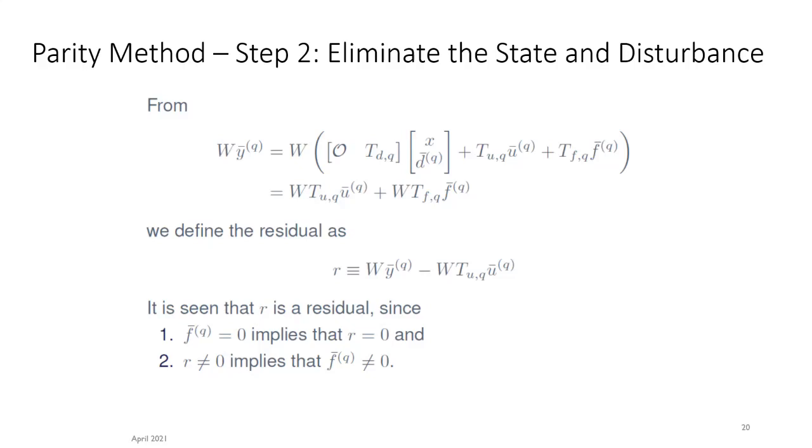Because that's the only term that matters, right? I mean, residual can include y and u. We don't have to have y and u in the residual, but if you think about that intuitively, you have a system and you want to know if a fault has happened to the system, and the only way we can do that is to look at what input has been and what output we have got, and somehow by investigating the input and output of the system, we can realize whether or not a fault has happened. So to use u and y is quite intuitive.